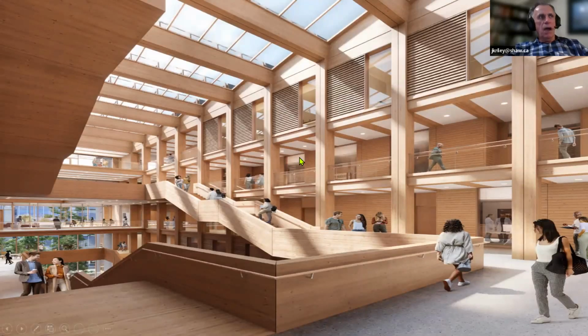Now, life science labs, in the design of these types of buildings, require no vibration, essentially what it is. Okay, IIC, STC, and NRC are all higher than normal offices. And what they've done here is accommodate that design requirement, L over 600, L over 800 in some parts of the building here. So this beam design here is exceptionally stiff.